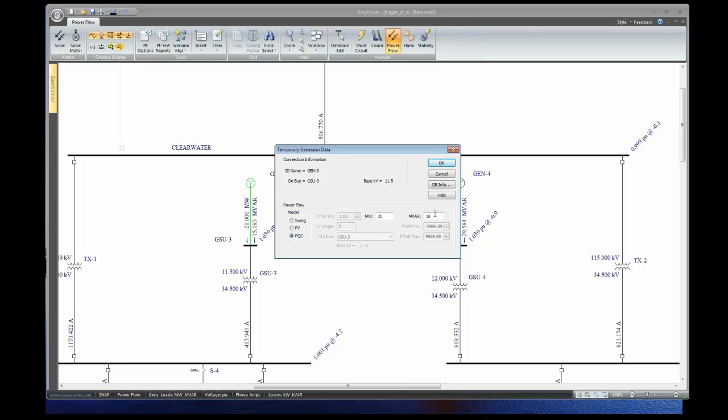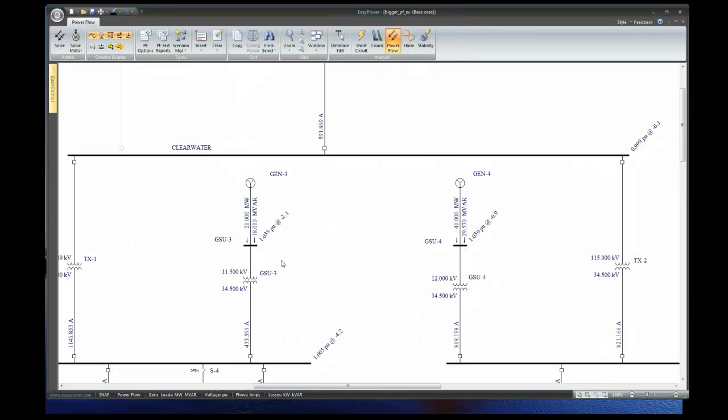So this is pretty much analogous to being in power factor control mode, if you're familiar with that, or VAR control on a voltage regulator. So now when this runs, this is going to stay 20 megawatts and 18 megavars. You can see my voltage is starting to creep up here. So regardless of what happens to this voltage, this is going to stay the same.